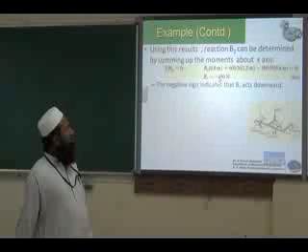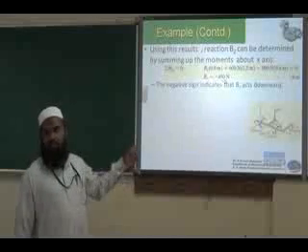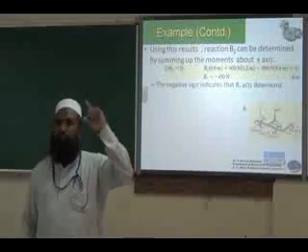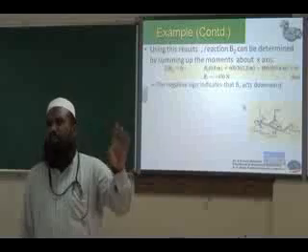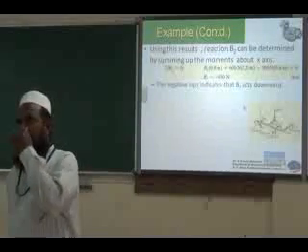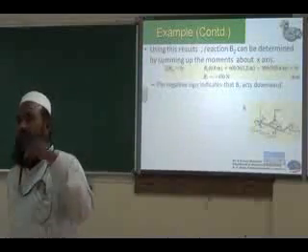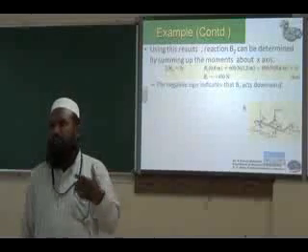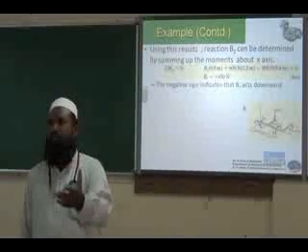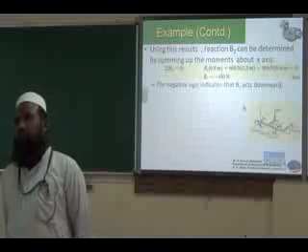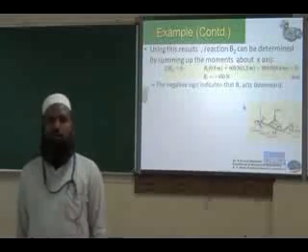So we got a negative sign that indicates that Bz is what we assumed is wrong. As I told you, remember, we just assume the reactions as upward or downward. If your results are positive, your assumption is correct. If your results are negative, the actual value is opposite to what you assume. Actual sense is opposite to what you assume.